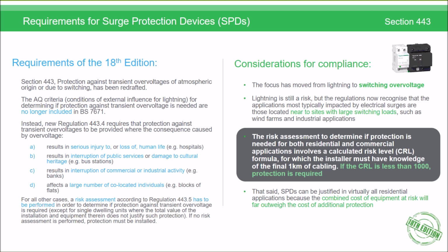So with that said, and the difficulties of conducting this calculation and formula, you probably see that surge protection devices can be justified in virtually all residential applications because of the combined cost of the equipment versus the risk, and of the protection of the additional device.